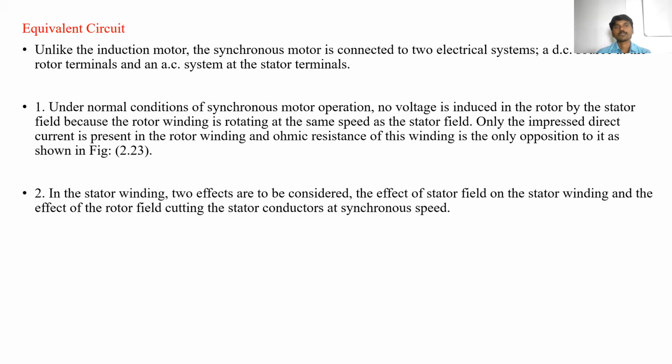So, unlike the induction motor, which, as we already said, requires only one supply, that is the AC supply for the stator winding only, in the case of the synchronous motor it requires two supplies. One is the AC for the stator, and another one is the DC for the rotor field winding.